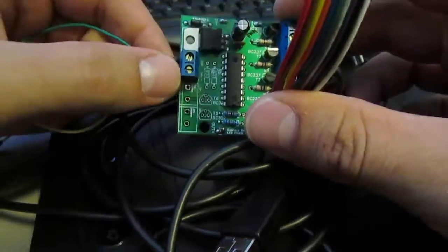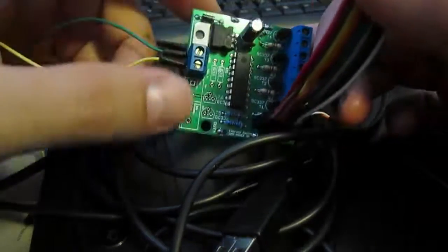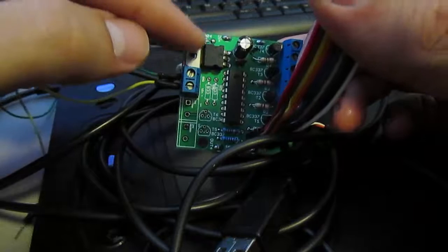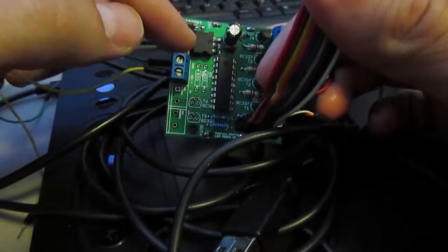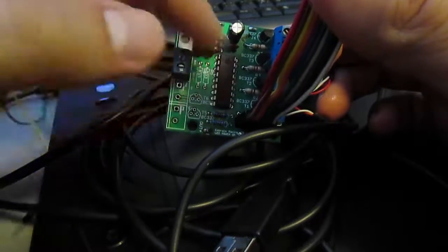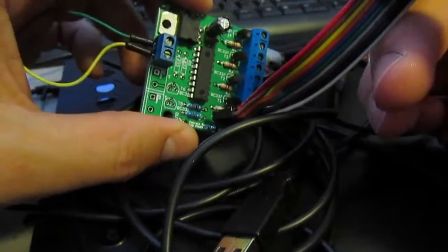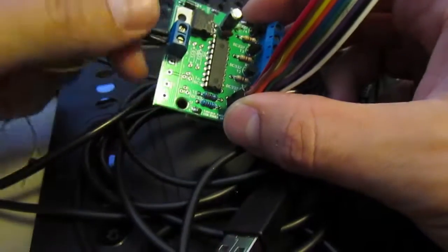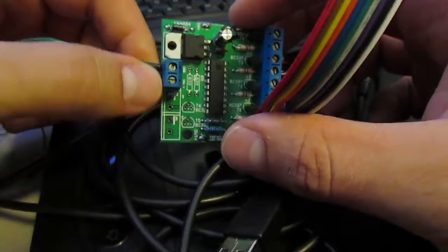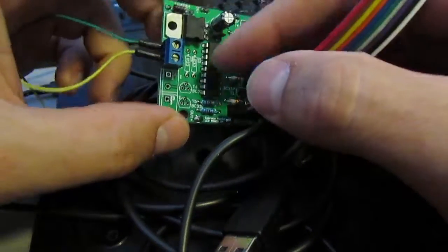So in this case, my adjustable voltage regulator on the bottom is set to output, I believe, 10.5 volts. So it'll output the 10.5 volts, and then our 5-volt regulator, again, which I showed you in the first video, will step down the voltage to 5 volts, and that will provide the PICAXE microcontroller with the power it needs while you program it. So those are the two requirements. Make yourself a little cable, super easy to do, and provide the board with 12 volts, and your voltage regulator will take care of the rest and power the PICAXE.